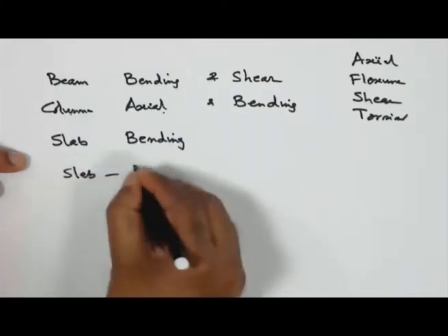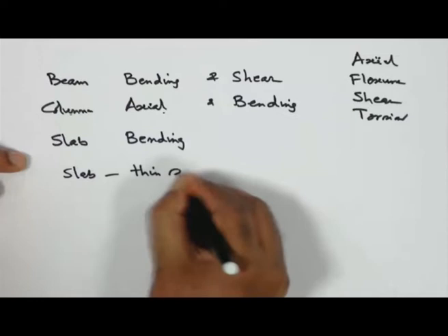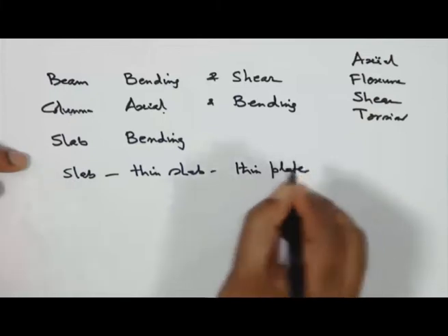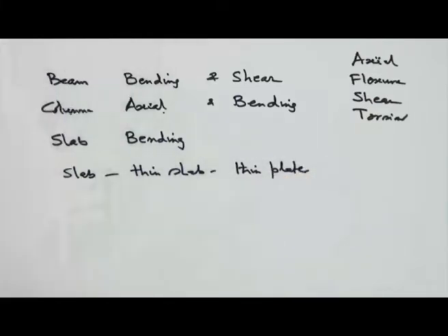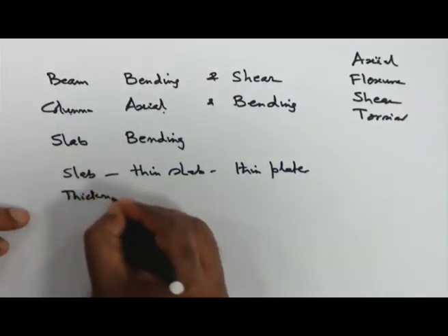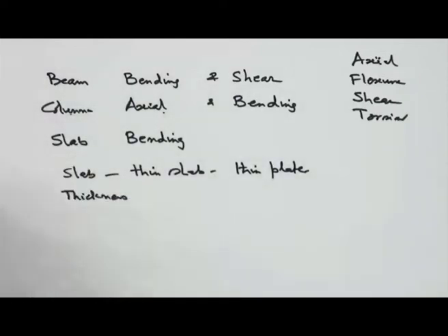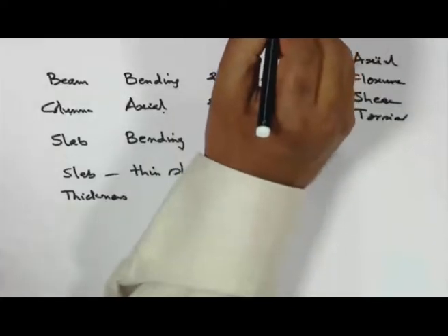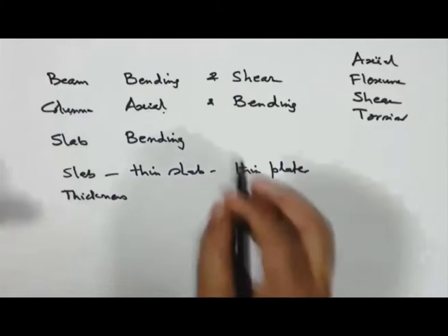Now coming back, I have just given you an idea. Let us quickly look at the issue here. First of all, please know your beam. I hope you have beam and slab cast on the same day from the very beginning, with the reinforcement not separate. Whenever you cast them all together, the slab will also contribute, and that is why we consider it here. But where shall we consider it?